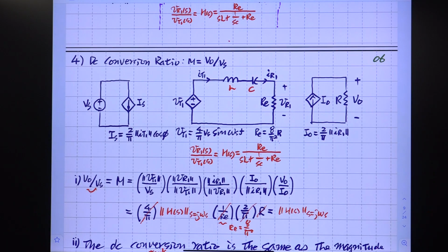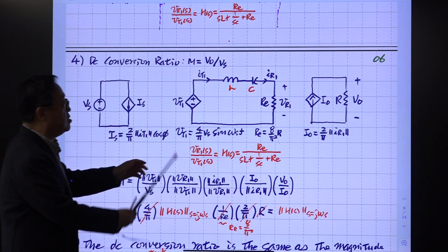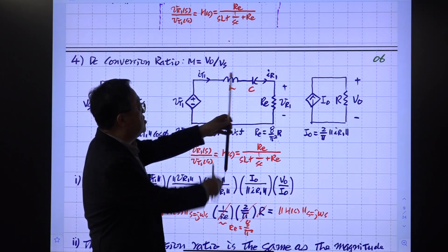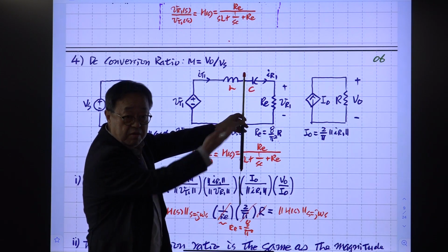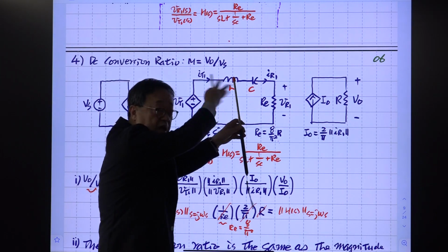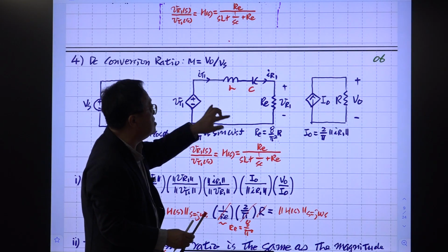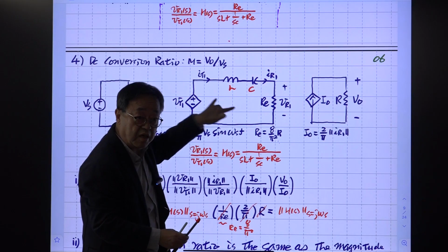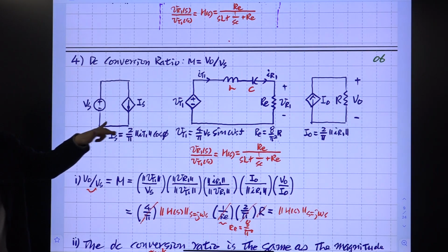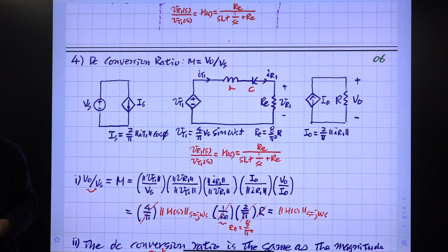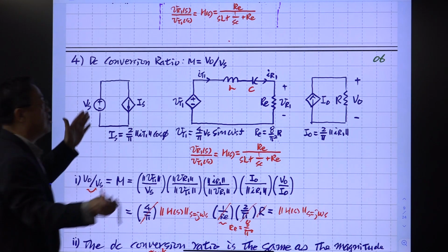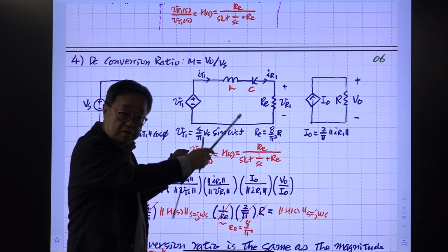Okay, for the parallel loaded resonant tank circuit, you have L and C in parallel with this. You just replace this tank circuit there, then you will get the same result. Suppose you have LLC, just replace this with LLC, then you will get the same result. LCC, same result. Some strange fourth order resonant tank circuit, just replace that circuit here and perform this AC analysis.